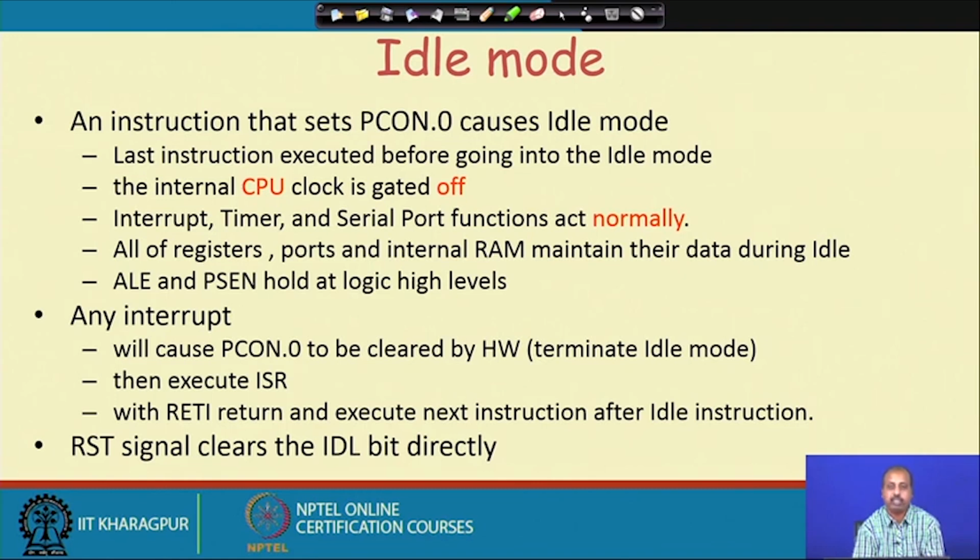That is very good, like if some event has occurred in the outside world, it will turn on the processor's operation. It will go to the ISR, and from that point onwards, whatever the processor was doing previously, it will continue with that. The instruction just after the idle instruction will execute on return from the interrupt.